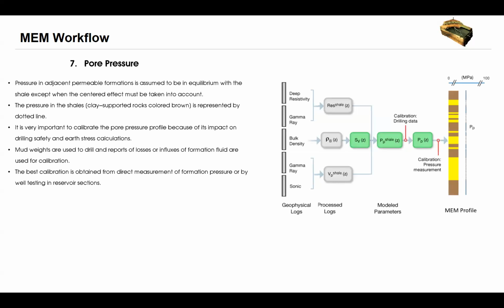We have some layers; you can pass through an overpressure layer and go to a hydrostatic one and vice versa. So the pore pressure is very crucial. I know that until nowadays we cannot get a real pore pressure calculation, but we can calibrate our data with mud weight or, like I have said, formation pressure to avoid misunderstanding of pore pressure.